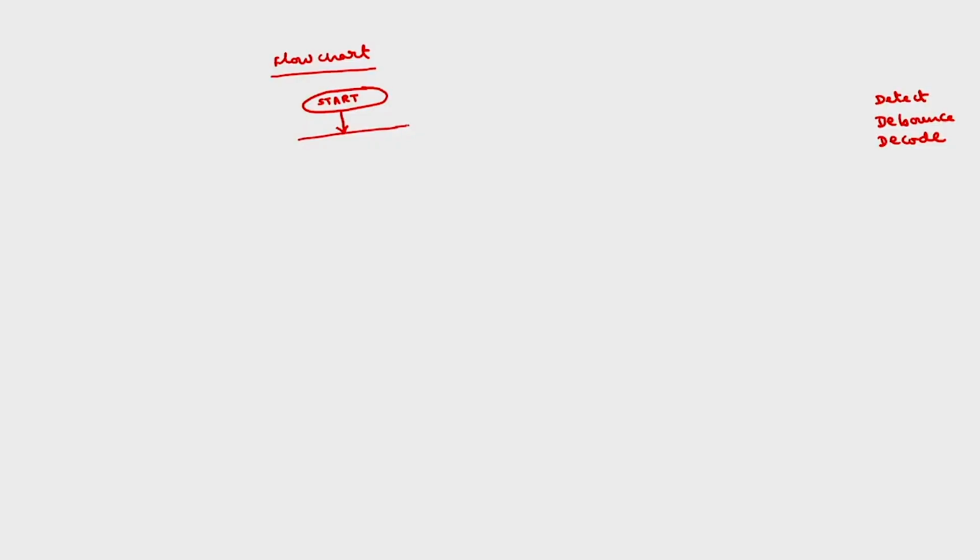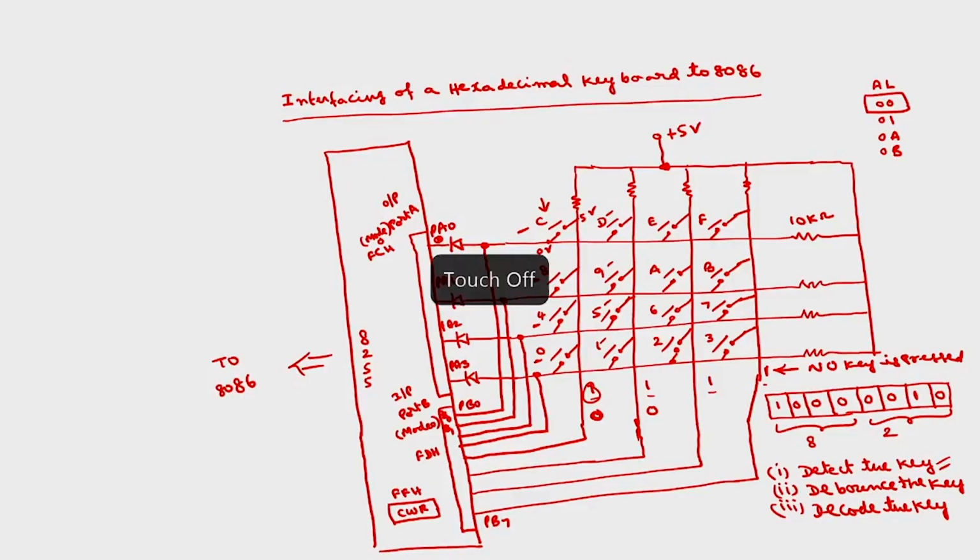Output 0 on all the rows. So, in the previous slide, first I am going to send 0 on all the rows. So, these diodes will be short circuited because this cathode is connected to 0, and the anode is connected to some positive voltage. Okay. These resistors are so selected that if I send 0 here, this voltage is greater than the cut-in voltage of this diode, thereby these diodes will be short circuited.